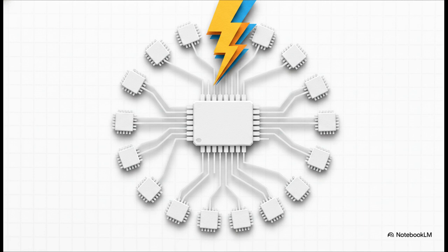To conceptualize CMOS fan-out, think of it like a single, highly effective teacher effortlessly managing a massive classroom of hundreds of students without even breaking a sweat. It can drive numerous inputs just effortlessly. Its only real Achilles heel, it's highly susceptible to electrostatic discharge. A simple static shock from your finger could literally fry the chip.